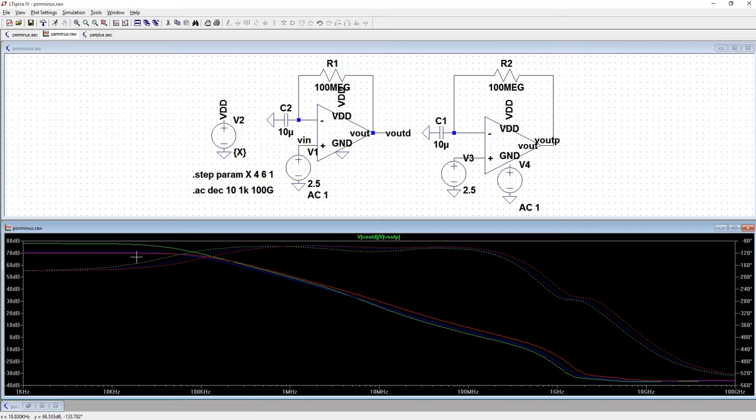It means that when you're doing a mixed signal design where you have both analog and digital circuits combined into a single IC, that if you were to have this transistor-based design as part of that mixed signal, the switching that happens between the digital signals will affect the power supply, but that power supply fluctuation isn't going to affect the output of your op amp, which is what you want. So this is good power supply rejection ratio.